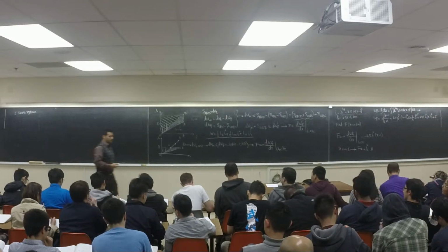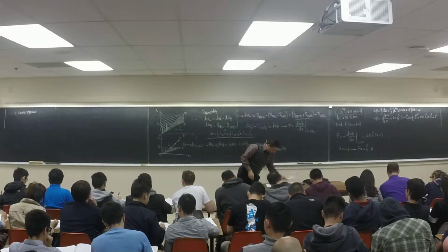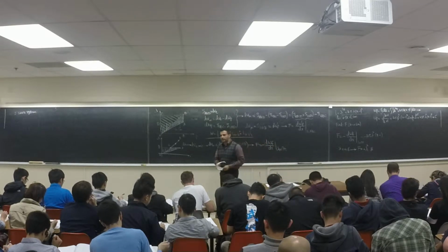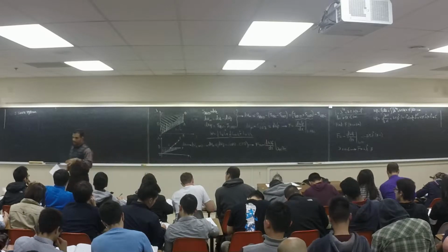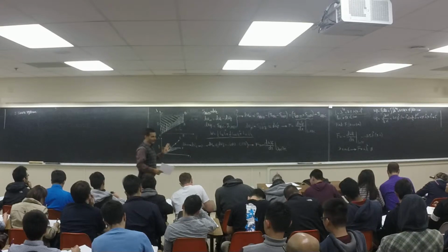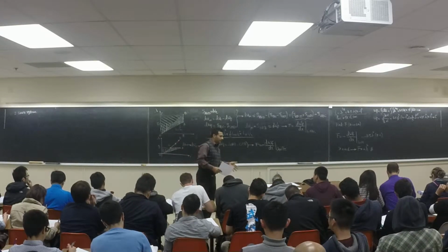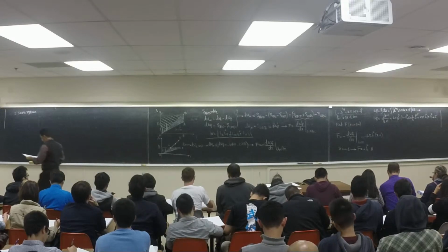Two-source system. So the story is going to be the same as the single source. Either we have a constant flux or we have a constant current. If we have a constant current, we should use the co-energy. If we have a constant flux, we should use the energy, right? So let's assume this one.